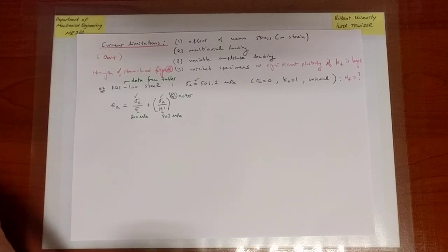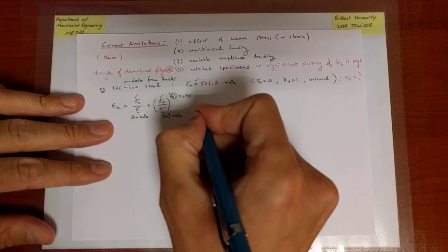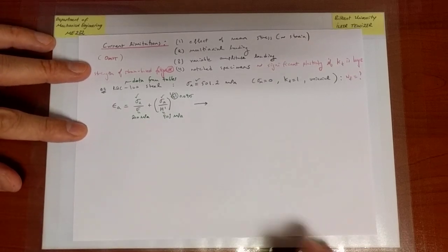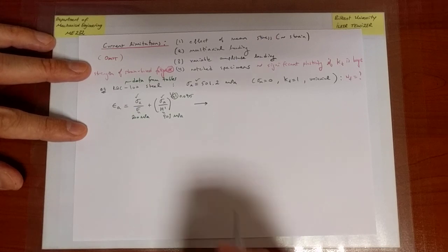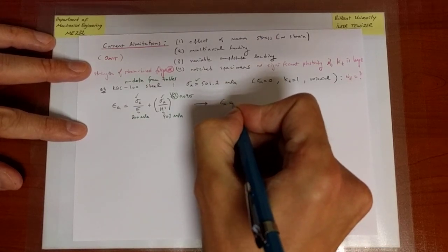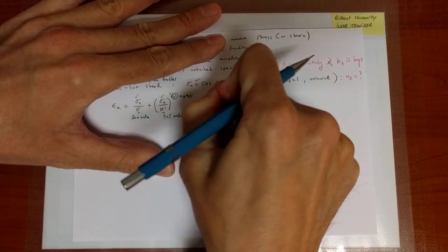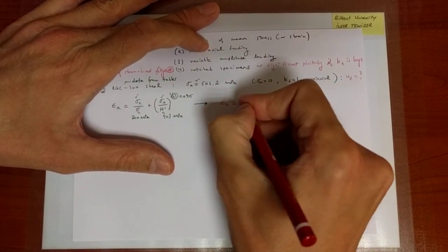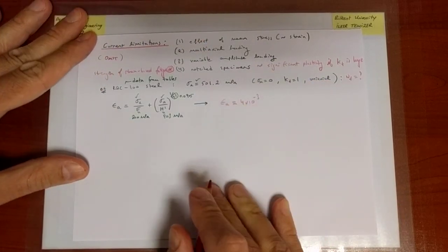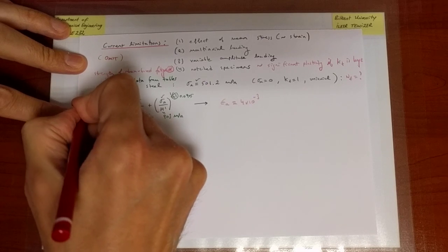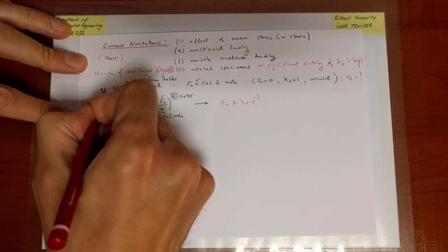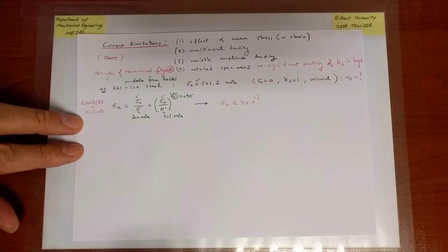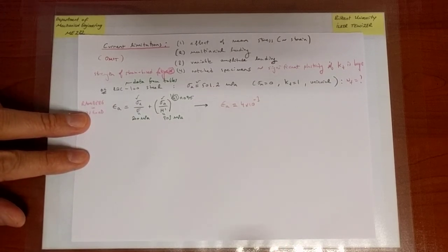Okay, so these being the material parameters and sigma A being given as 501.2 MPa from the cyclic stress-strain curve of the model through the Ramberg-Osgood relation, we can go ahead and directly determine epsilon A, which is equal to, let's write that in red, epsilon A is equal to 4 times 10 to the minus 3. Okay, so this is, let's say, a Ramberg-Osgood type relation. Now, having that result at hand allows us to continue into the second step.